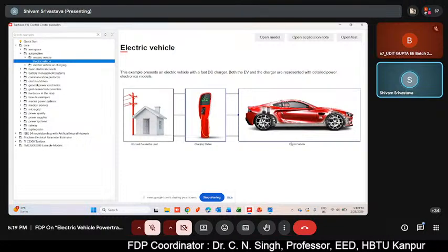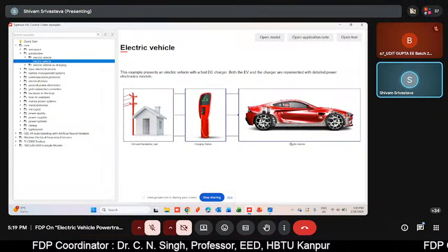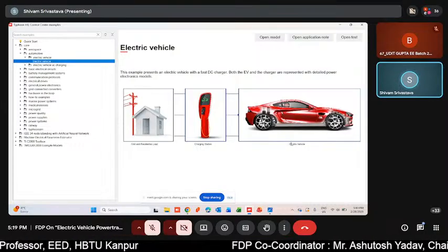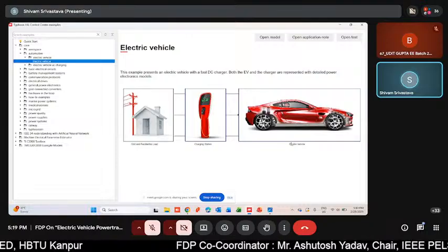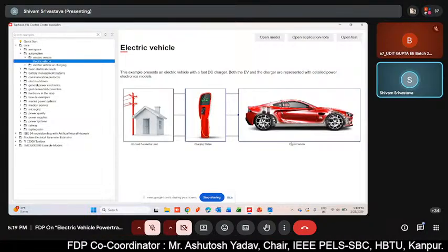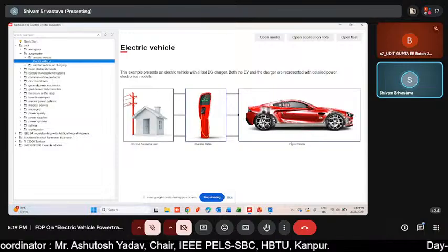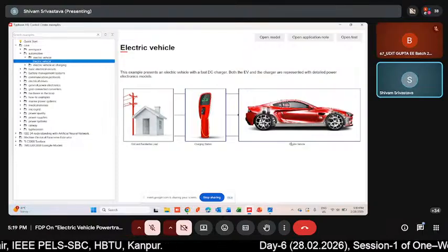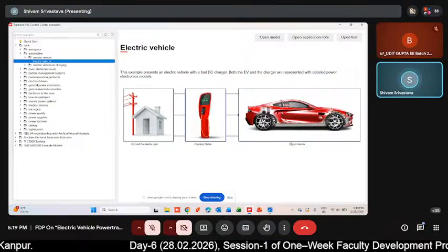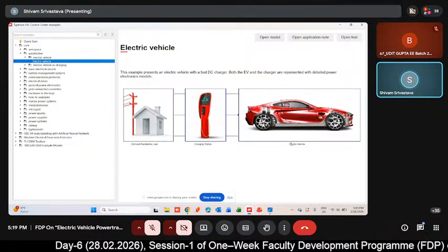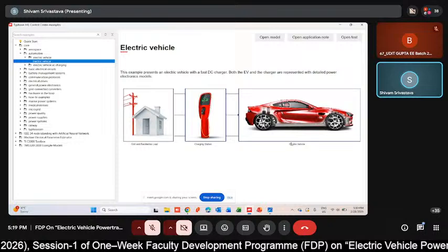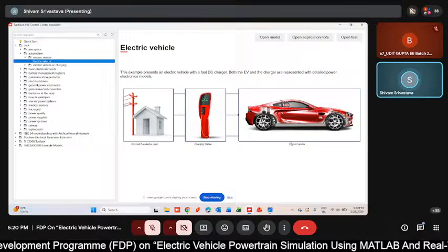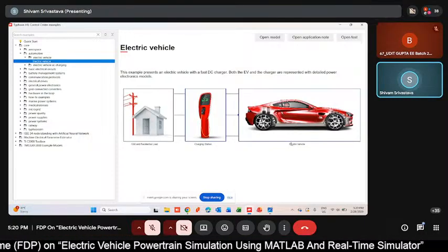For the charging scenario, we have a battery charger of 175 kilovolt-amperes, implemented using the battery inverter component, which you can simply drag and drop from the library section. This battery inverter component, used for the battery charger, supports grid forming and grid following modes. In grid forming mode, the inverter acts as a voltage source, while in grid following mode, the inverter acts as a current source.